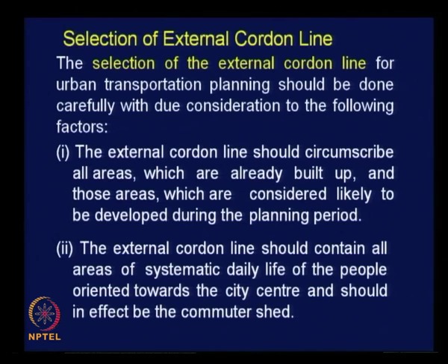If there are people commuting on a regular basis from a small suburban pocket, even though it is isolated from your main city boundary, that suburban pocket should be included in your planning area, because that pocket is contributing regularly on a regular basis to the travel pattern of your urban area, right.